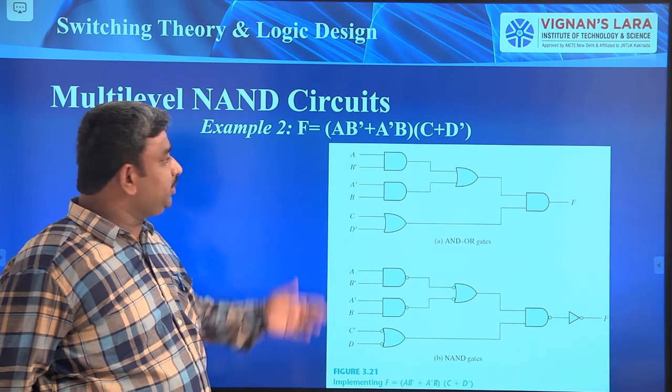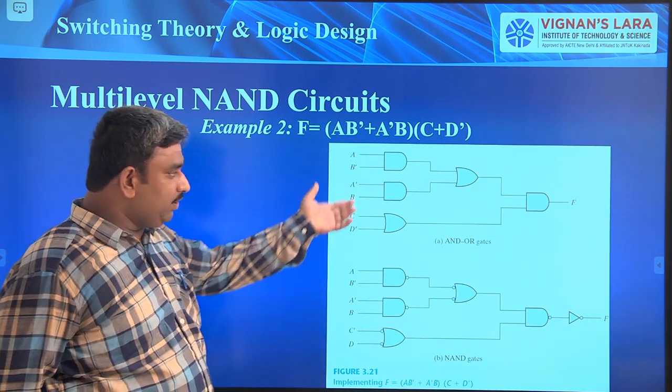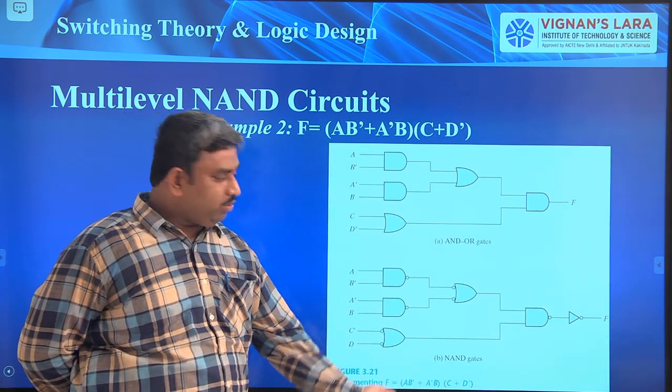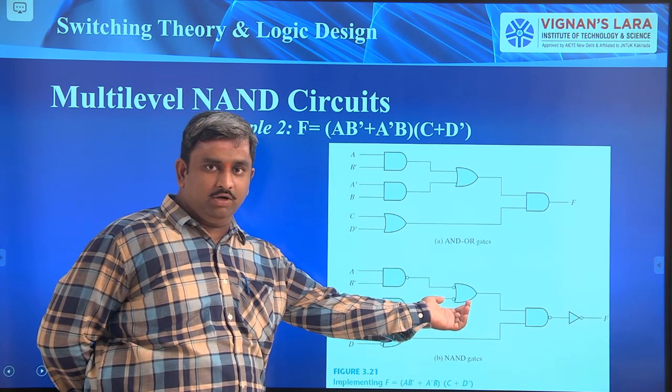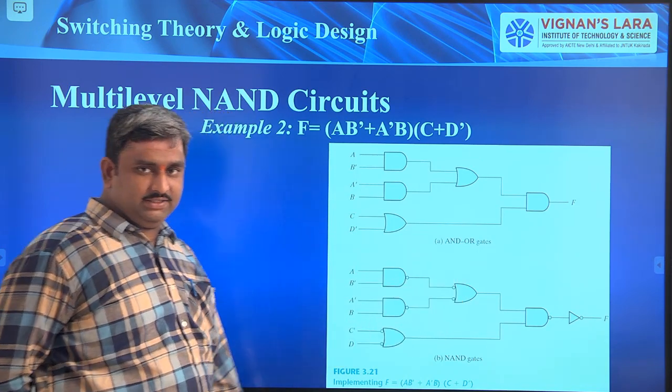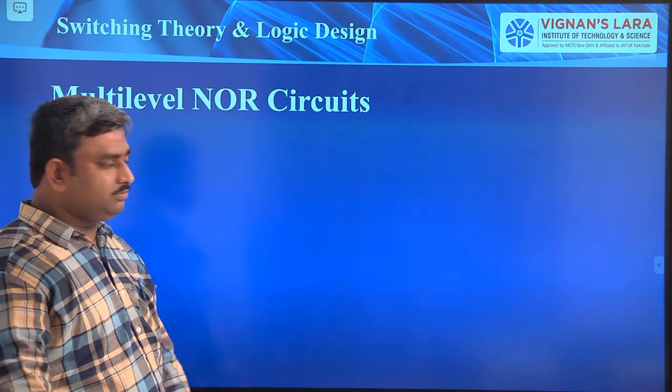So this is a solution for this given problem. I have given the first step, second step, third step, just to replace these bubbled OR gates with the NAND gates. So that is the final step.